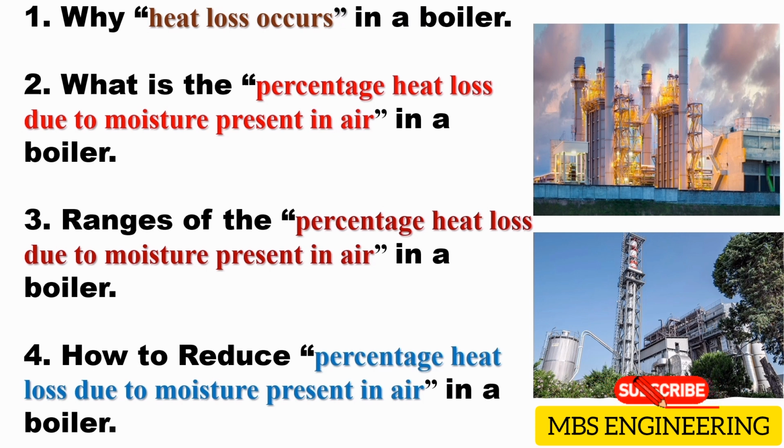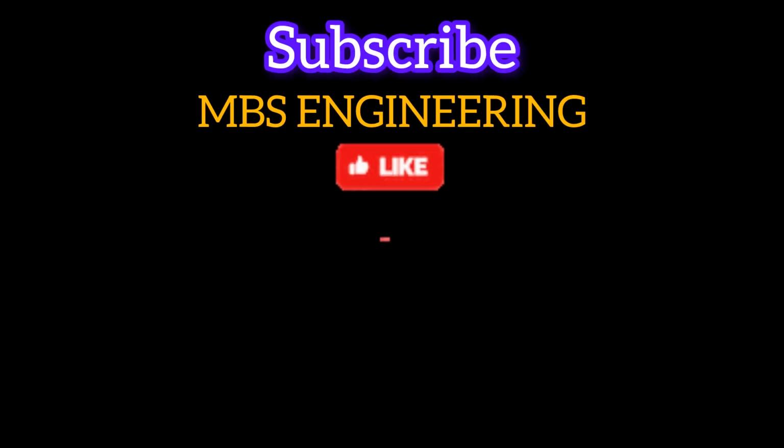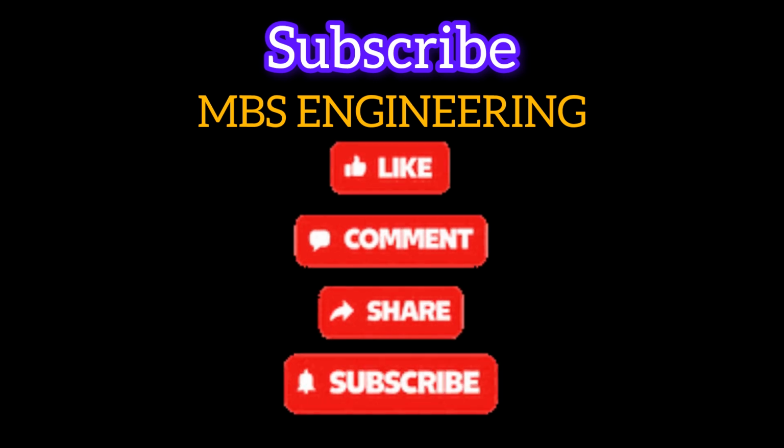Effective strategies include using preheated air, drawing air from dry sources, and optimizing air supply. By applying these practices, we can significantly improve boiler efficiency and reduce energy loss. We hope everyone learns and understands the percentage heat loss due to moisture present in air in the boiler.